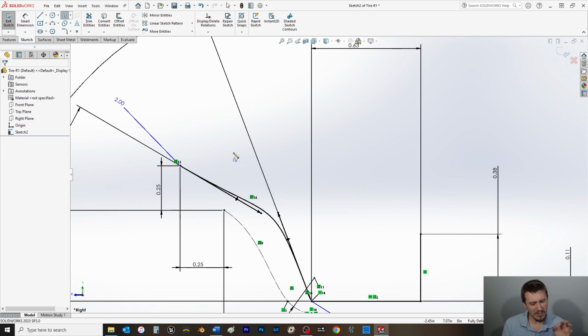I don't usually like them. They can be very difficult in certain situations to dimension in actual drawings. And in certain cases, depending on whether the spline is something you created or gets generated automatically based on the model's contour, they are not able to be dimensioned whatsoever. I'm not going to show you that in this video, but in a future video I'll show you that, and we'll look at how you work with that or workarounds for that. So, for now, we're going to just stick in our modeling space and continue on.